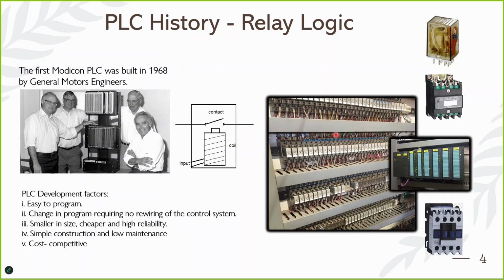These types of relays are usually mechanically engaged. So if you're in a control room that has this old relay logic, this is a simple image here, and you apply voltage across its coil, you will hear the sound when it engages. You hear ta, ta. So imagine you have a process that is engaging many of these things. There's a lot of noise generated in the control rooms. And because they are mechanically engaged, they break down easily and require a lot of maintenance.